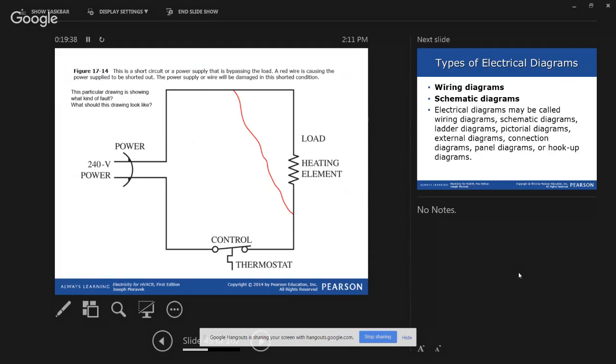But in the case of a ground fault, instead of going from 1 meg on the normal stance, in a normal stance being 1 meg, this will go from 1 k ohm, or even on a fluke meter, or even I think your guys' meter has the points. This will read down into just the 100 or significantly lower. You'll know. You'll be like, oh man, that seems like it's low.